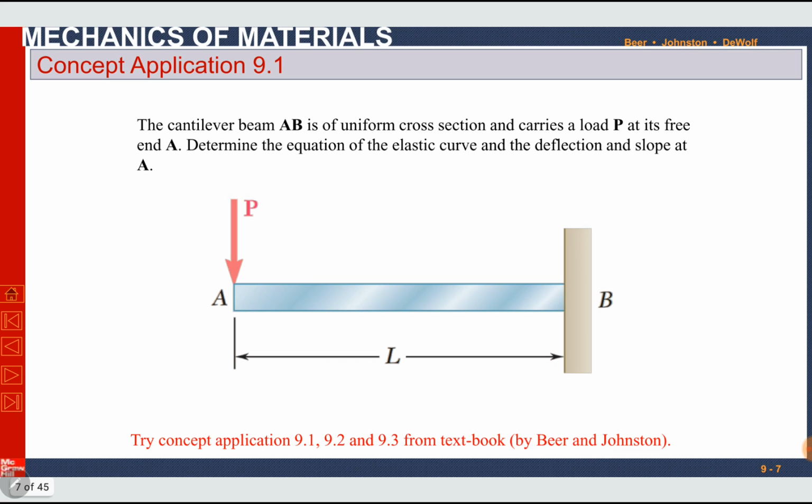Okay, here's an example problem. It is concept application 9.1. Very important. The cantilever beam AB is of uniform cross section and it carries a load P at its free end A. Determine the equation of elastic curve and deflection and slope at end A. What is the equation of elastic curve? It is very important. It will be asked in almost all of the questions. Equation of elastic curve is equation of y as a function of x.